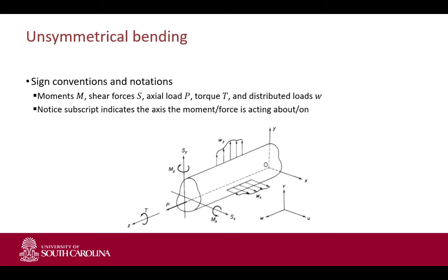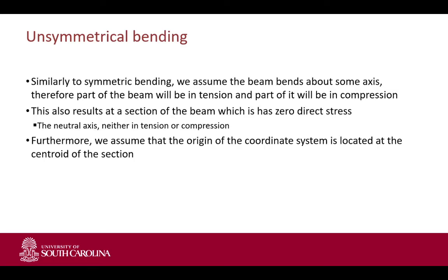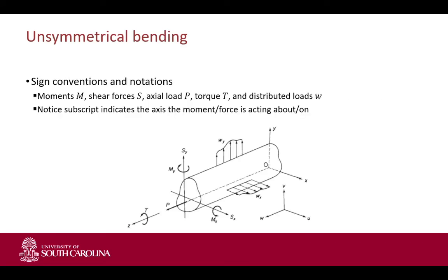For torsion, in this case, the torsion T is nothing else than an in-plane moment, so it could be substituted by a moment around z. It's basically the same. For those three, the sign is determined by whether it yields tension in the positive quadrant of the two-axis system.